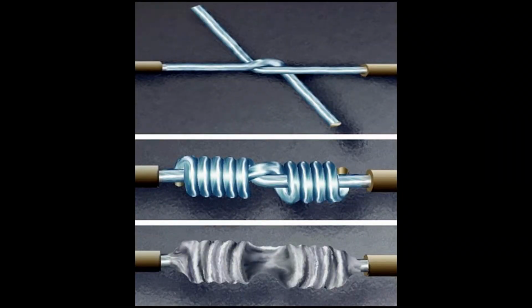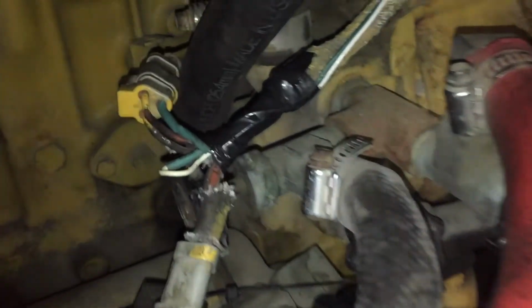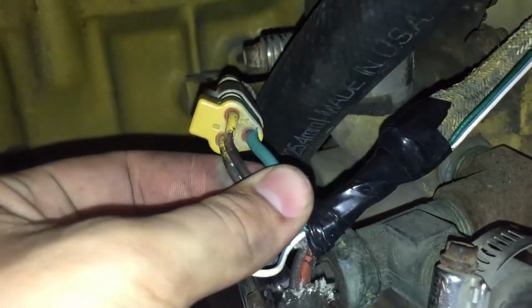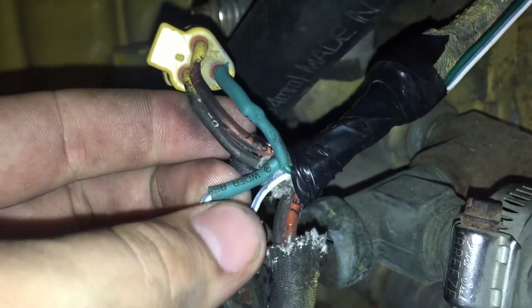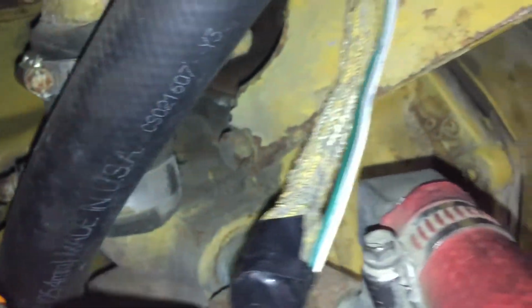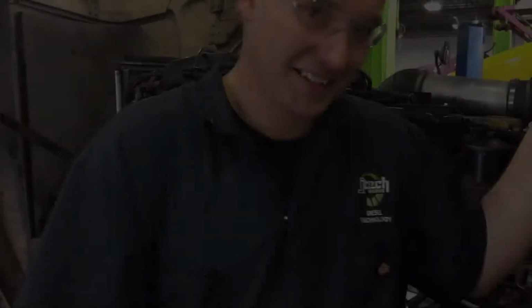Another way is soldering by twisting the wires and using heat shrink as well. But some things to consider when doing this are the size of the wire. It needs to be adequate, both length and gauge, and also the routing of it as not to get it too hot or exposed to moving parts.